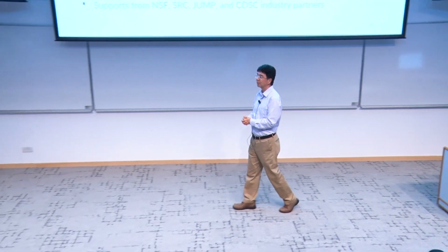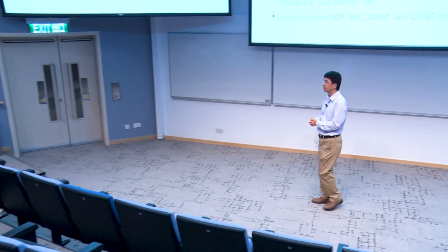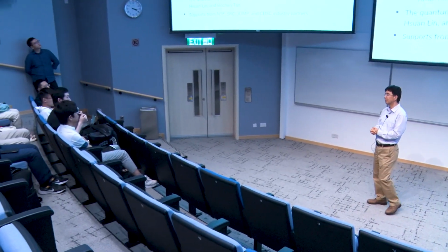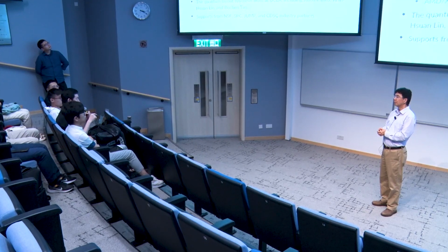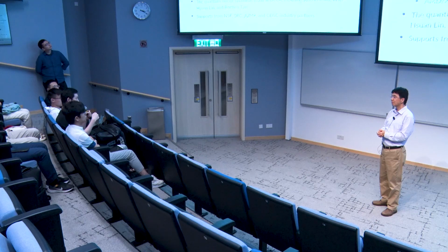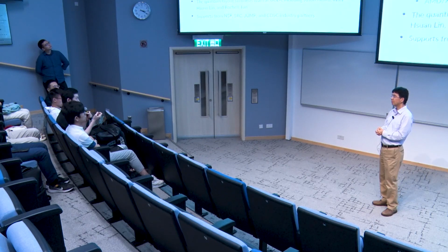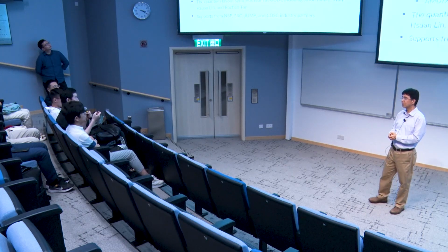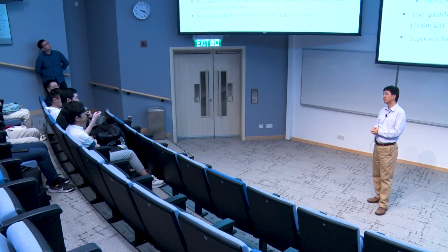I actually have two questions I want to ask about the interconnection and TAPA. The first one is, for example, on the U280, there are three super logic regions. When you do data flow crossing the super logic regions, the timing is usually hard to optimize at a very high frequency. We have a project where we build an RTL kernel across these super logic regions and send data through all the dies, but it turns out the timing is really bad.